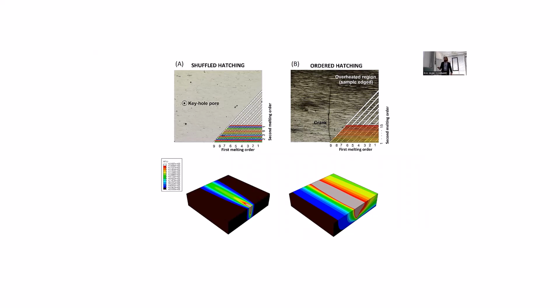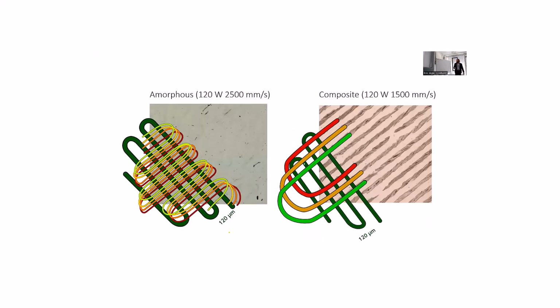Of course, we did some simulations with our friends from Carolina. We can say that in a single line, we can really consider the melting as a single thermal event. Whenever we have this one well solved, we can do whatever we would like with the microstructure. In this case, we have to struggle with porosity here and crystalline phase here, and our processing window gets narrow. But if we use this double melting strategy, first the green big line, we just pre-melt the powder, make it kind of bulky, and then we can do some magic.